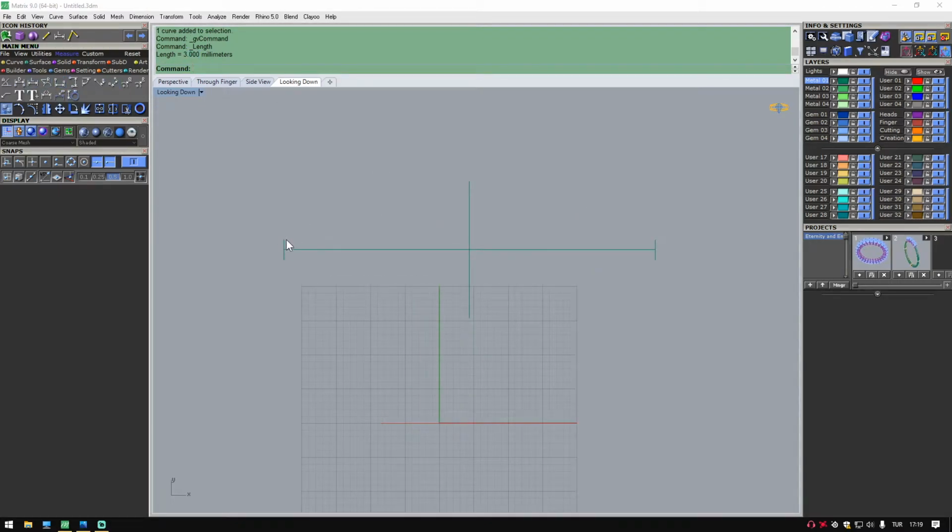Okay, now I want to combine this end with this one, but going in an arc like so. So you can go to Curve and use this command for arc direction. And if you check your command line up here, the commands will always tell you what to do next. It says start of arc, starts here, end of arc, ends there, and now direction. See, I want something like this. No big deal. Just anything you feel comfortable.